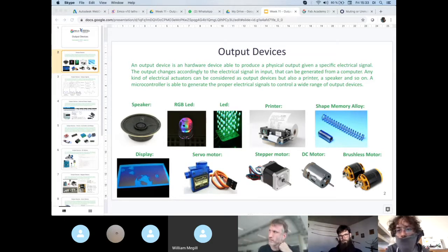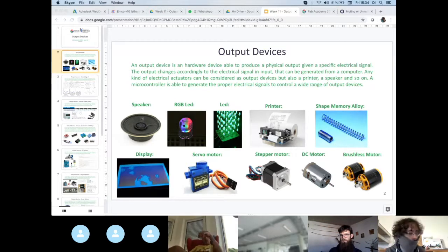So in that machine, to move the X-axis very fast in engraving, we have a servo motor instead of a stepper motor. Also, big CNC machines are coming with big servo motors nowadays in comparison to traditional stepper motors.